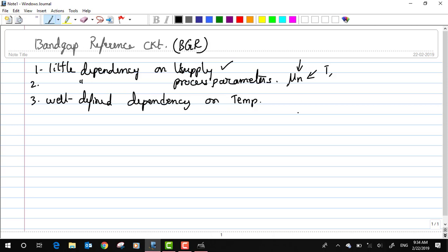And the third category is, as I said before in the second case, that we have to build the circuit using transistors, and these transistors are sensitive to temperature. So basically the process parameters in general are sensitive to temperature. Now first we need to understand what the relation is between the temperature and the transistor, and I want to create a circuit that is independent of this temperature.